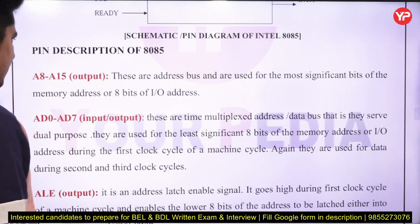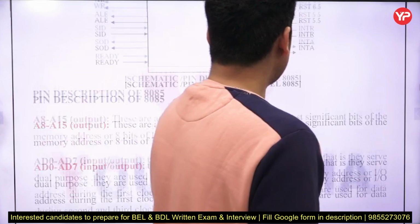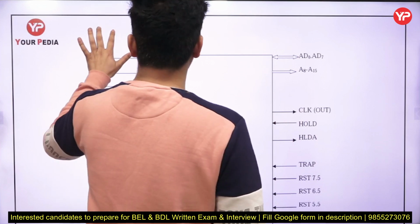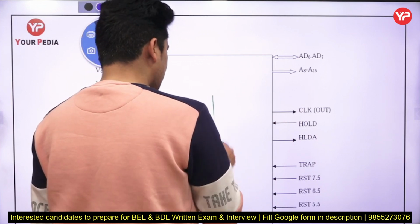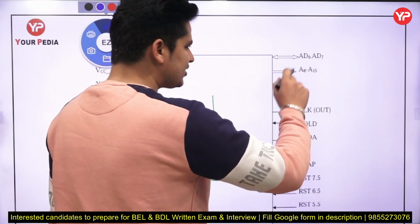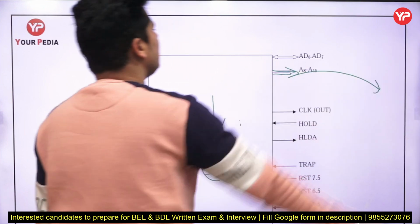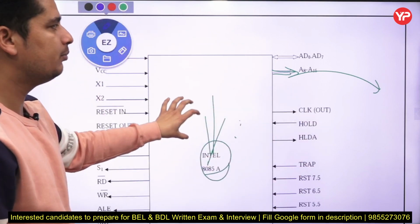So here are A8 to A15. These are the output pins. Can you see the arrow here? Each pin has an arrow that shows where the data is going from and to. Basically, in 8085 this is the microprocessor. If you are connecting a memory and you send the address of that memory, the address will be sent by 8085 to that memory, and it will enable that address, take the data from there, and provide it to the microprocessor.